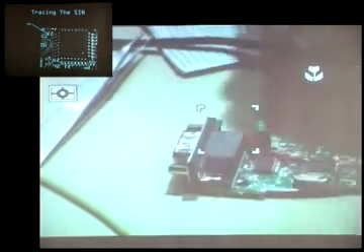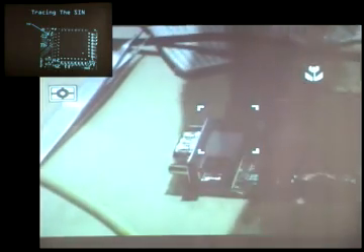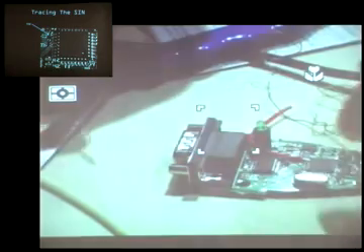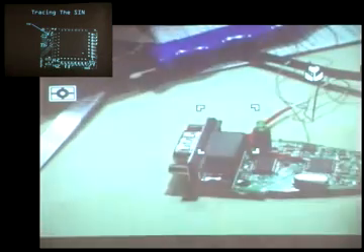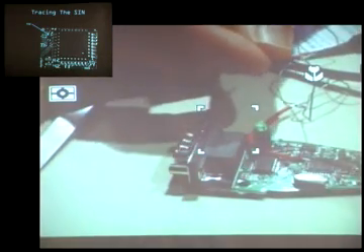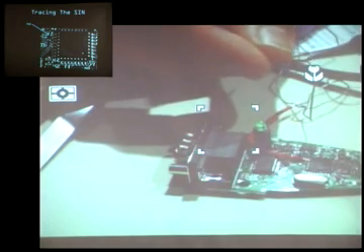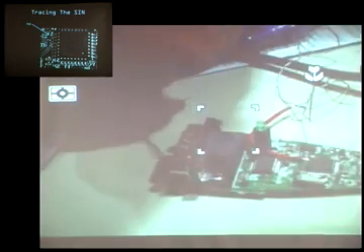So I'm just cutting that about the same way. Cut off the other end for that. Go ahead and add a bead of solder to this one here. Can you guys see this at all? Yeah. Alright. And so now this one's going to be a little more challenging because I'm now trying to solder a pin that's between two pins.